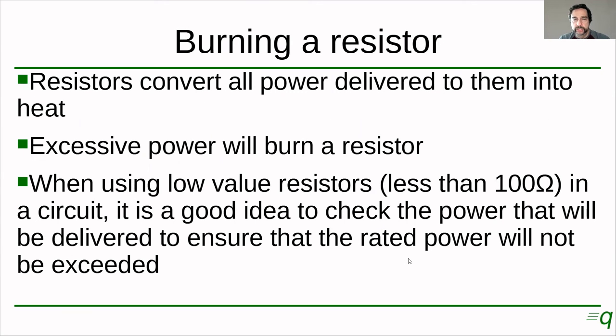Resistors do not normally deliver any useful power output, unless you're building a heater. In a resistor, all energy is converted to heat, and excessive power will burn a resistor. This matters when using a low value resistor of less than 100 ohms in a circuit, assuming we use circuits with lower voltage, like 5 volts or around those values.